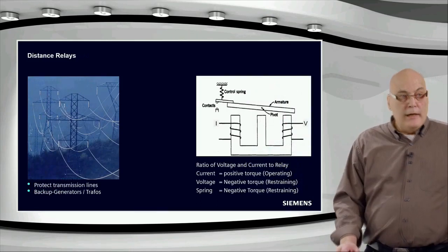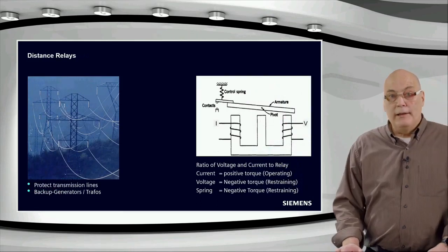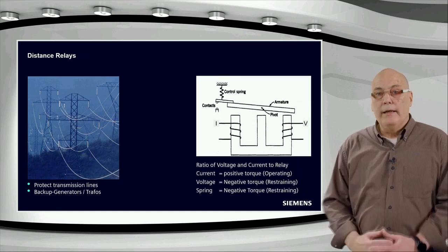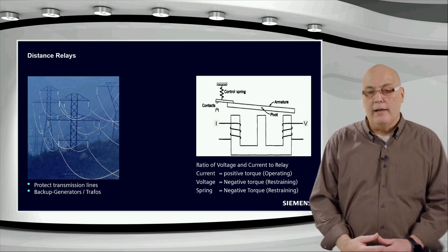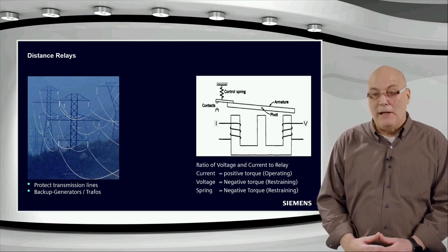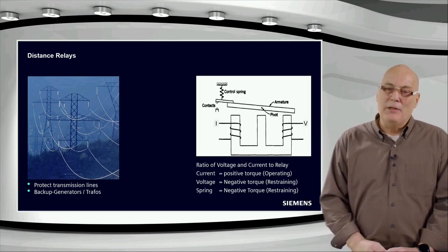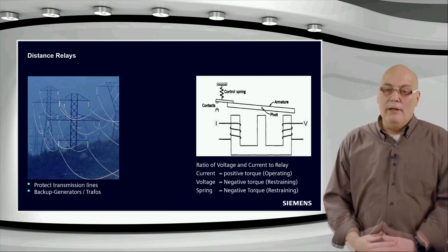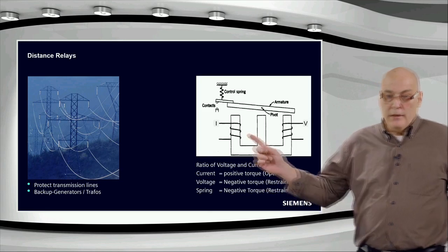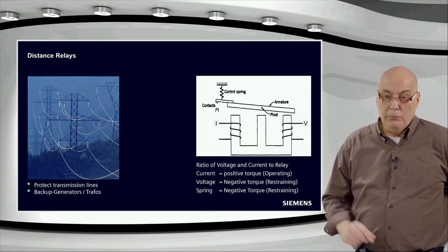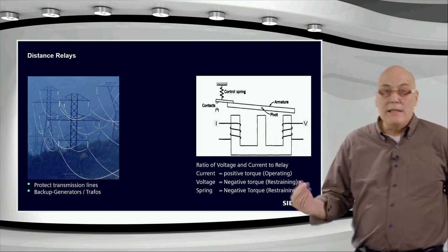From the early days, we saw earlier on the diagram, I said in the early 1920s, we did not have any electronics as such, transistors and that type. At that time, it was electromechanical. And you see a little diagram here showing how, roughly in a schematic way, a distance protection was constructed. You see there are two windings, a current and a voltage winding. As you see, the two measurements we used previously for the impedance protection.